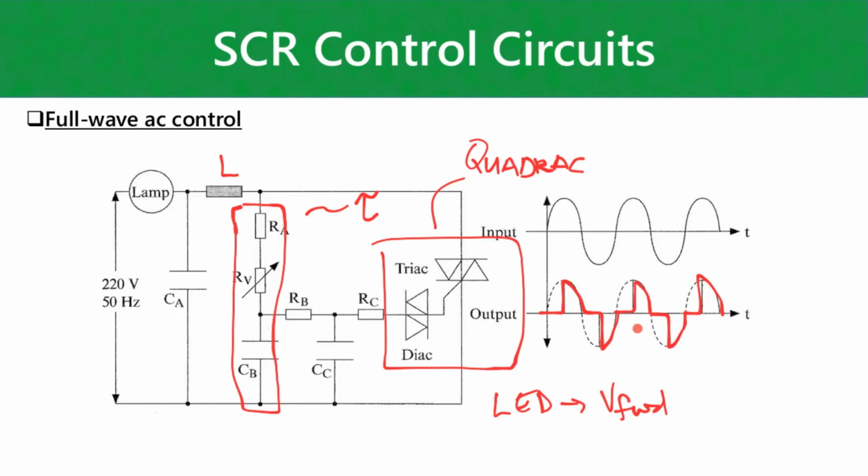So you're not going to change the forward voltage drop of the LED, but you will be able to have control over the average current flowing through it, and thus you can control the brightness of the LED in that manner. There are a few ways to do it. The problem is the circuit that we have here is more focused on changing the voltage level and not the current level. So you are going to struggle a little bit with the LED lamp to adjust the brightness.